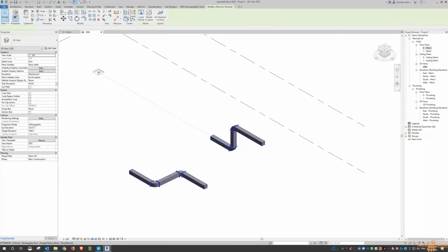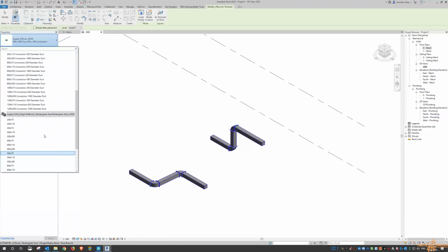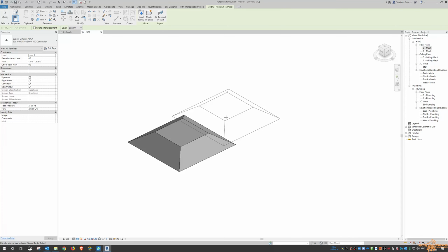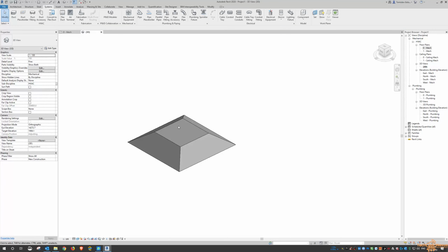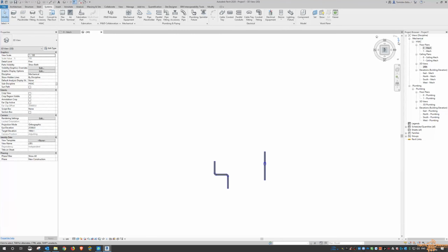And there's also air terminals, but again, there's a whole bunch that are included in there, and you can just come in and grab your own, or grab them from a manufacturer's website if they've got their own as well. So I always say that to everyone, if they are going to be using Revit, to have a look at the manufacturer's website. They might have a lot of their families already loaded.